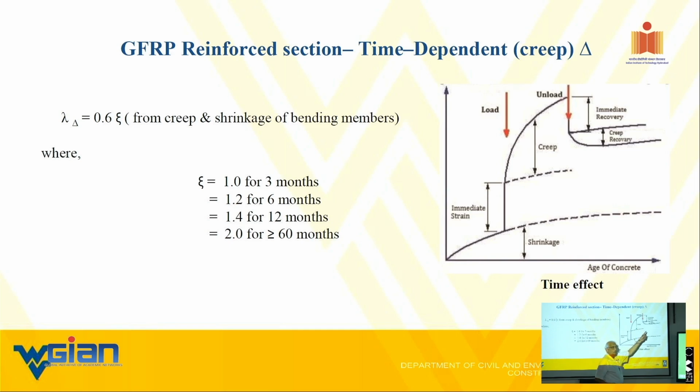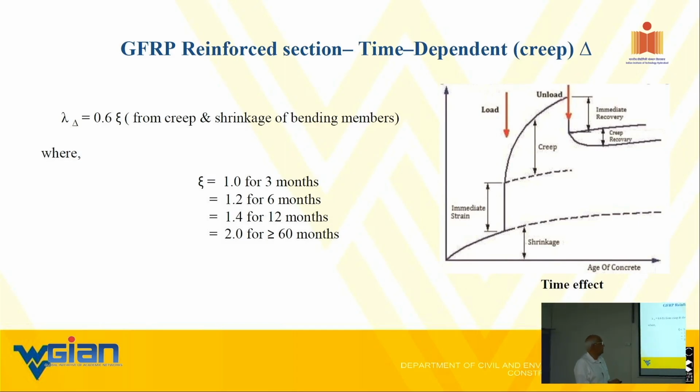When you remove the load, the recovery will never ever be back to 0. When you remove the load, yes, there is some recovery, but that is less than the creep deflection, which is from here to there. So these are some of the issues to keep in mind.